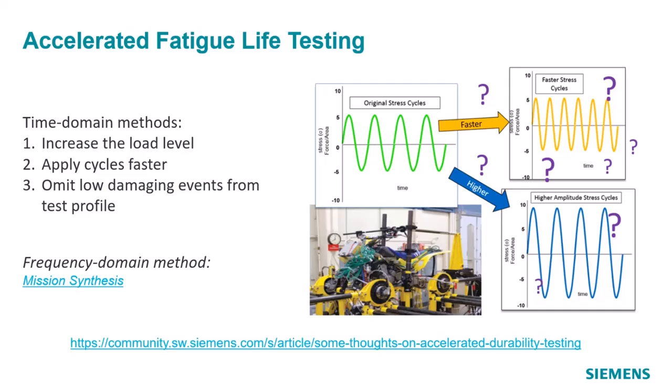Even after you have collected the loads from the proving grounds or from the real life operation of the vehicle, like driving on the common highways or on other road surfaces in the case of automotive, going through the process of testing for that long using that time history can take a lot of time. So you want to come up with a way to accelerate that test so that you can do the test in a smaller amount of time.